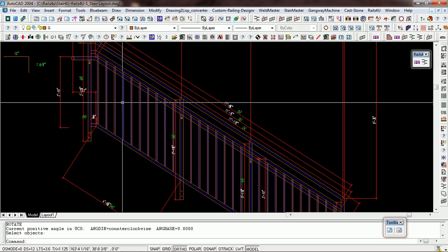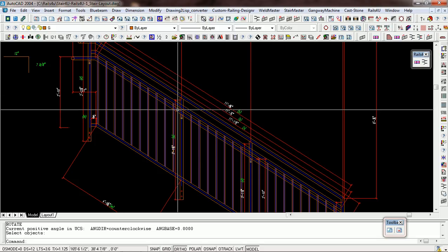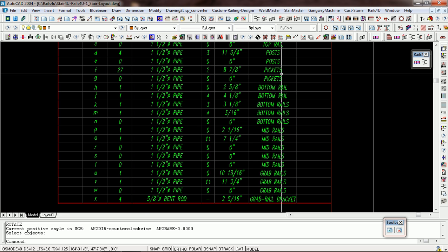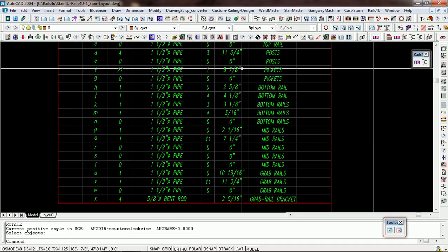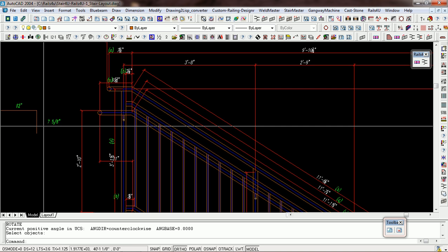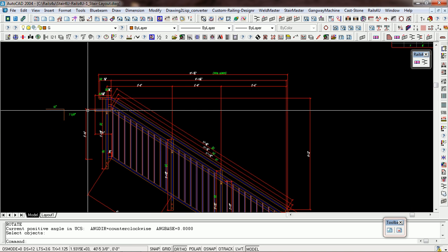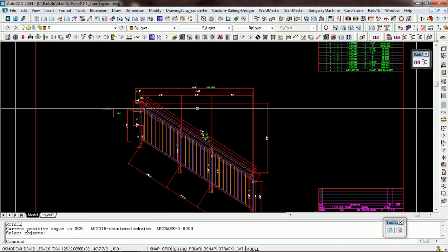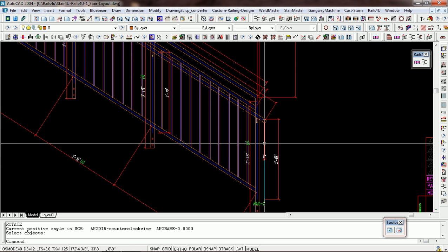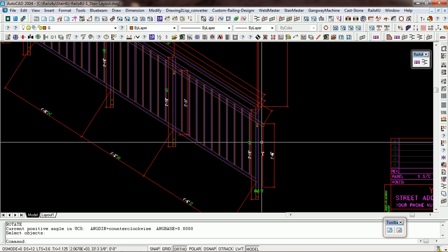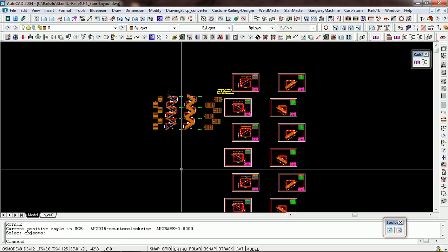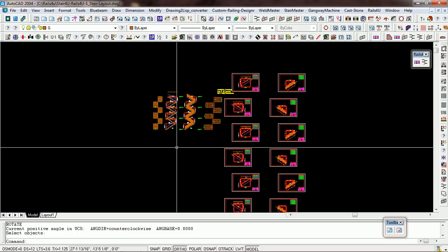everything should be fine. It's going to give you the post lengths, picket lengths, 2 foot 8 7/8 for the length of your picket, and you use this rise run for the angle, which is easy to find on any of these items. If you know anything about trigonometry, if you have a calculator that is a construction calculator, it does it for you very easily, very quickly. So basically, we've done a stair 3 stories high.